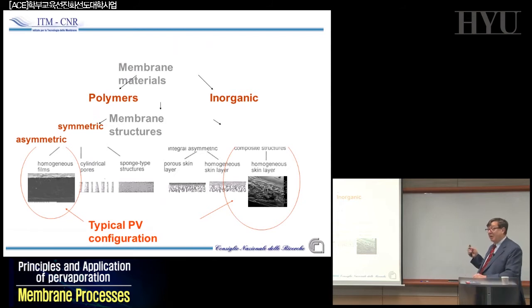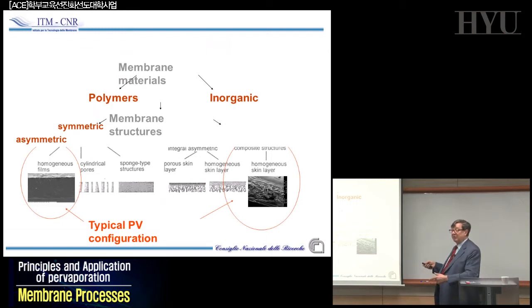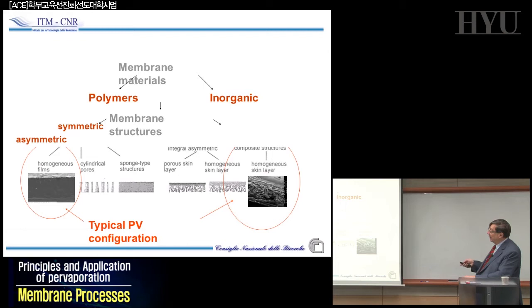We understand that now the material is very important, because the material is the one that is giving the benefits. If we want to overcome the azeotrope, we need a system in which one of the components has to be more soluble or more permeable, and the other one less soluble, less permeable. Remember that one term is diffusivity, the other one is solubility: chemistry and kinetics. And many different kinds of membranes can be prepared for pervaporation.